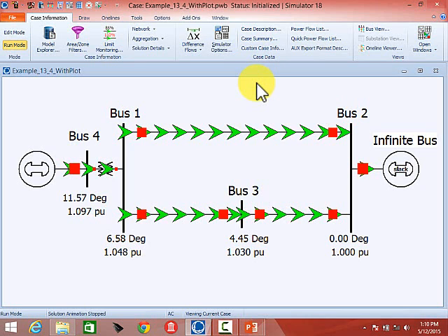We just have a generator connected to something called an infinite bus. Infinite buses don't exist. They're something that usually you just run into in an academic setting, but because PowerWorld Transient Stability got its start as an academic tool, PowerWorld does directly support infinite buses. So in this example, we're assuming this bus is an infinite bus. All that means is that its voltage, magnitude, and frequency are held constant.